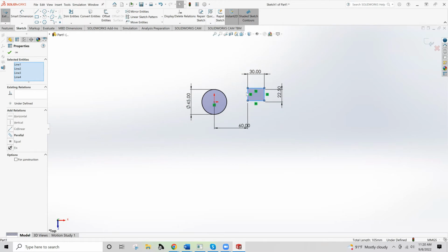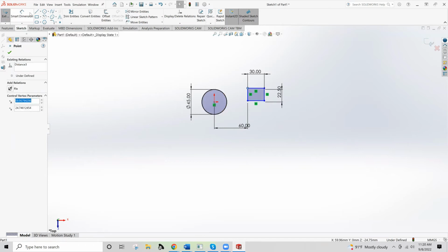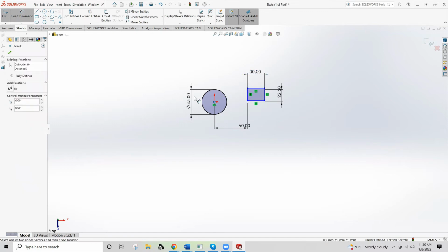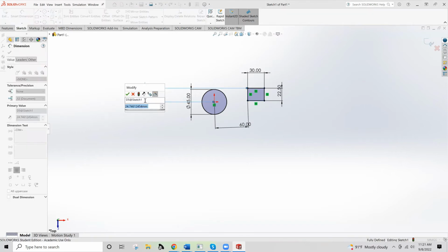So instead, we also need to define how far away it is by selecting our smart dimensions and telling it here what this distance is. So you have a couple different options in terms of how to define these and how to pull the leader lines out. You just want to pay attention to the difference between horizontal, diagonal, and vertical, because those are very different kinds of dimensions. So right now, this is the one that we're missing.